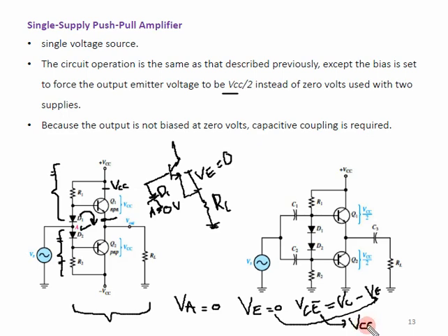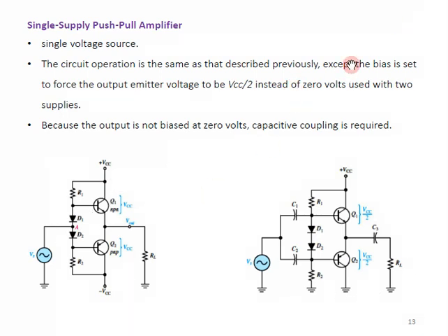This is VCC. So what is VCE now? VCE would be the drop over here between this point and this point. This is your collector point and this is your emitter point. That's why we call it VCE, between these two points. VCE is equal to VCC.